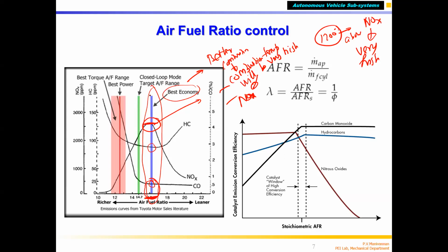That's what you can see in the violet color line. Here, in a very small region, the combustion level is very high, correct. Because of that only you have better thermal efficiency. High temperature means more pressure is created, correct. If more pressure is created, more downward piston force is created, correct. So that is converted to torque. That means more torque, correct.